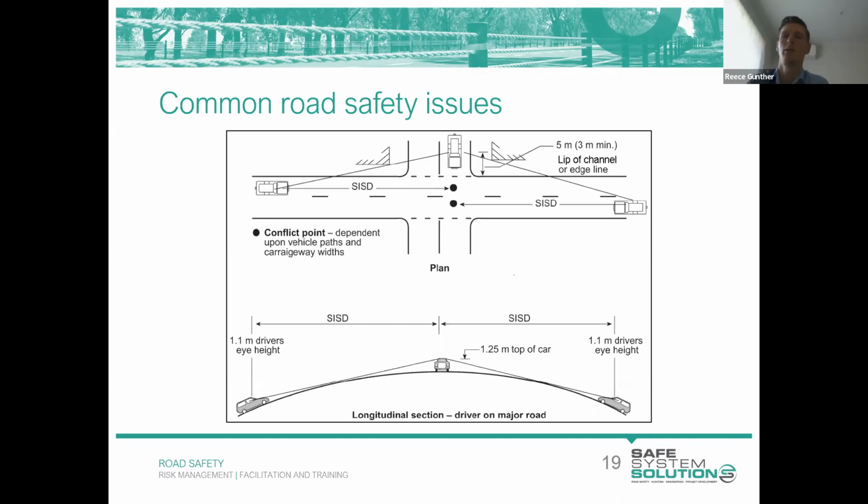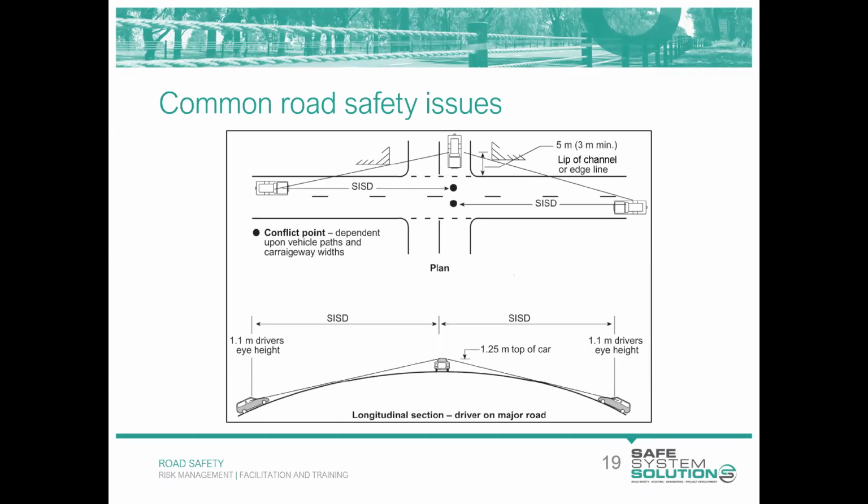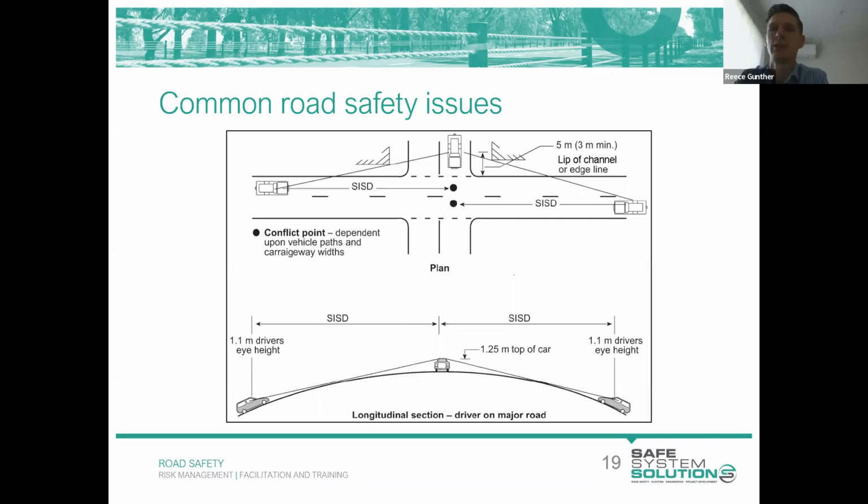Yeah, good question. So lane splitting is an issue where we've got large vehicles creating large envelopes at our intersections, or we've got large traffic lane widths. For treatments at the intersections, the way we can avoid lane splitting or sharing is adopting what we call mountable areas of curb, or so-called aprons and the like.